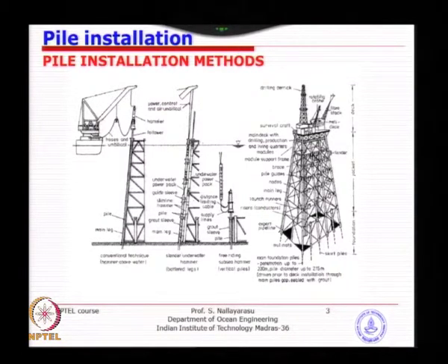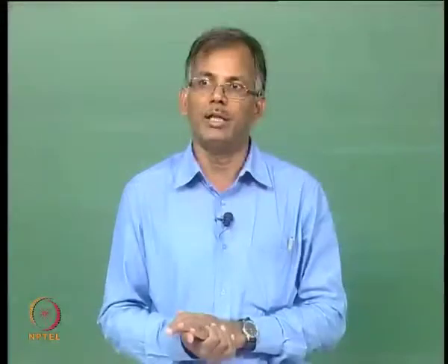So, that is why for such a problem you need to over-predict your self penetration. That means you will have an upper bound solution and a lower bound solution. You can use a stronger soil and find out what the penetration is, which will be the minimum. You can also assume the soil is weaker, same material, so you have 2 sides of the story.